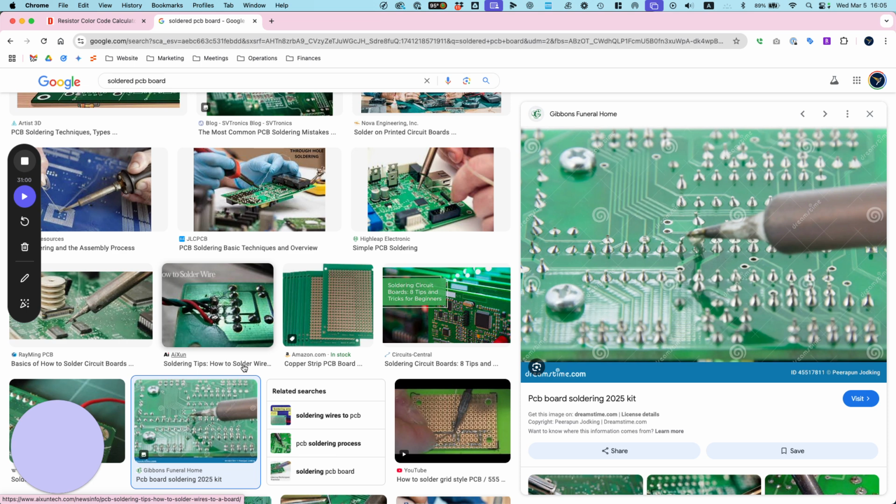Good. This one's a little bit too much solder, and now I'm concerned that they're actually touching. I found the resistors for it. You might need to remove a little with the sucker here.